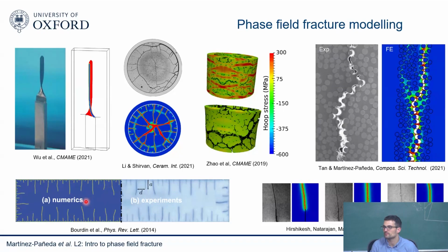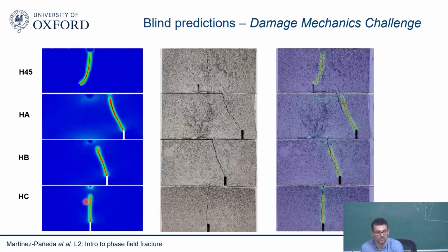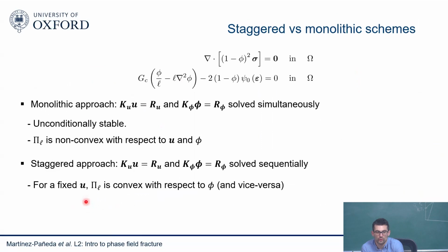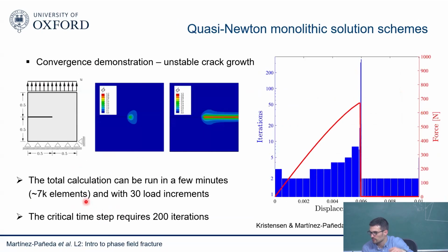For the monolithic scheme, in the phase field, what is the influence of the tolerance values? Is there any significant influence? We use what comes in Abaqus by default. So you don't have to do anything about that. You're welcome to play with those things if you want, but you don't have to do anything special from your standard values. It's fine.